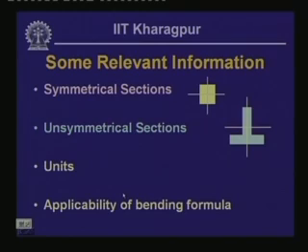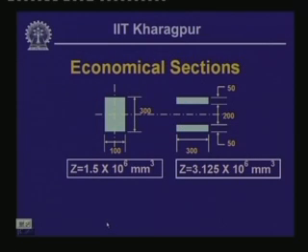But in general, a beam has its length much larger in comparison to its cross sectional dimension, and hence the error in evaluating the stresses with this assumption is insignificant, and we can neglect that. Hence, we can apply this bending equation even if we do not have pure bending in a particular segment of the beam. If the bending is non-uniform, even then we can employ this equation without losing much accuracy in the analysis of the stress. So this is very important: though we derive the equation for pure bending moment, we can apply it in other areas as well, where the beam is not truly acted on by pure bending.